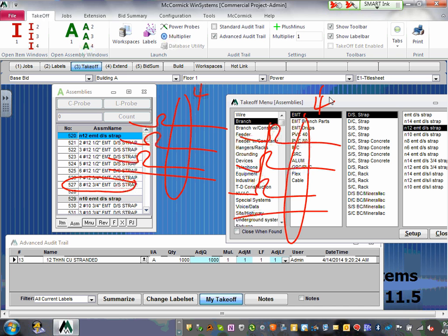6 circuits. You can get 6 circuits because you need 1 conductor for a neutral, right? So why don't we make it easy? Move with 6 circuits. Here's the 6 circuit. You're looking at it, guys, right here in your hand. I have more extra wires though. 6 circuits, 8 conductors in an EMT conduit.